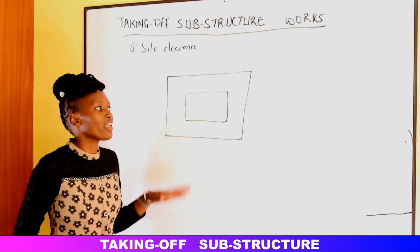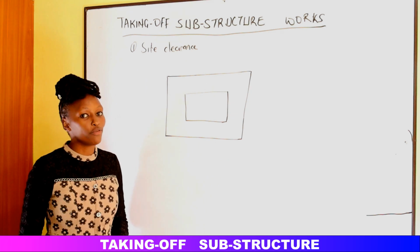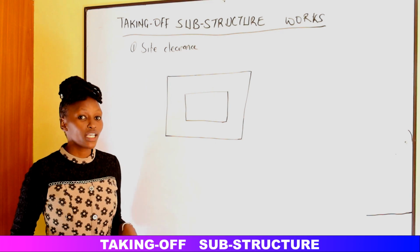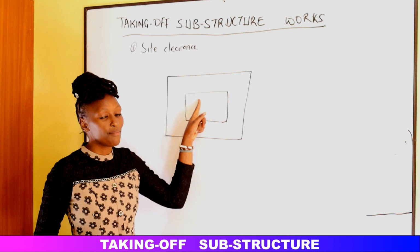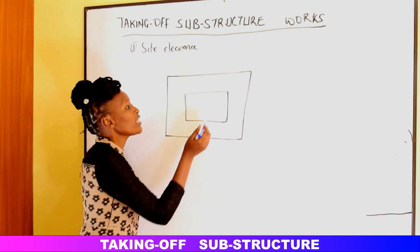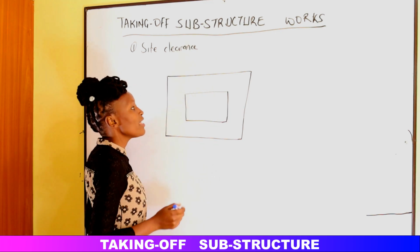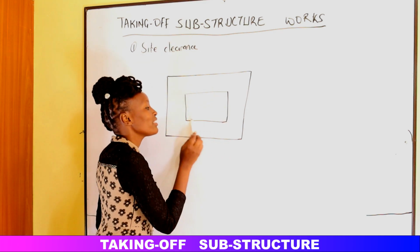Definitely, we will clear the whole site. But when it comes to doing a bill of quantities, a BQ, when we are taking off, taking off is just measuring. We will measure only where the building occupies. We will not measure the whole site. Maybe the building is rectangular. Then we will bear in mind the walls of the building are like this.